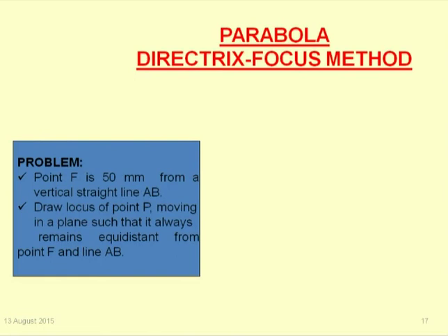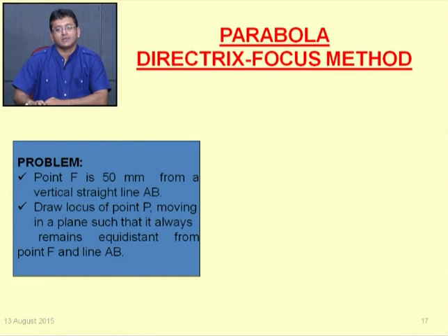As we know, in the case of a parabola the eccentricity value is 1, because here a point on the path of the curve is at an equal distance from the focus and the directrix. So let us take a quick review of how to draw with directrix and focus, which you already learned in ellipse. The same method you have to apply to draw a parabola.